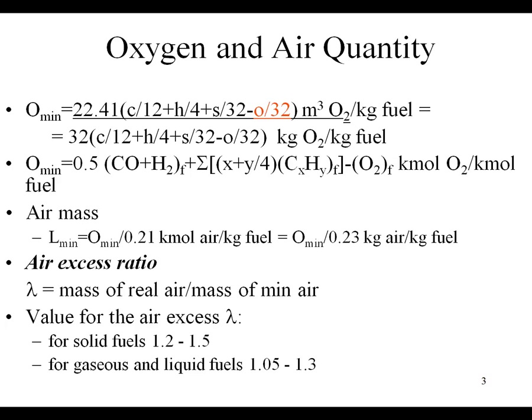And in order to avoid this possibility, you use stage combustion or low combustion burners, meaning that for a particular time and zone in the combustion chamber, the air excess ratio is less than 1. Under these conditions, the nitrogen doesn't find any oxygen to go into the reaction, and it remains molecular nitrogen. It will not be in the chemical reaction.